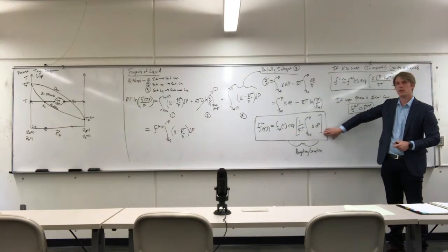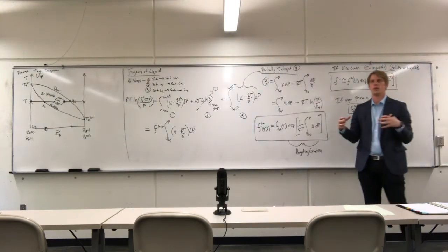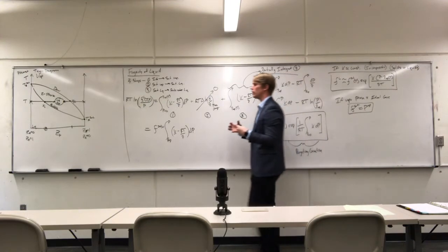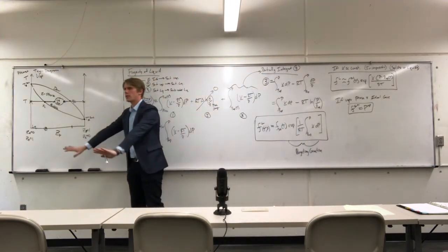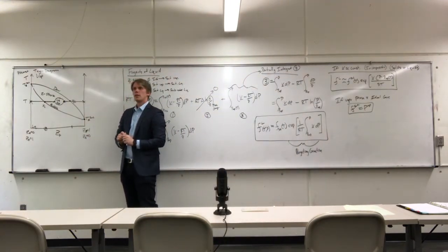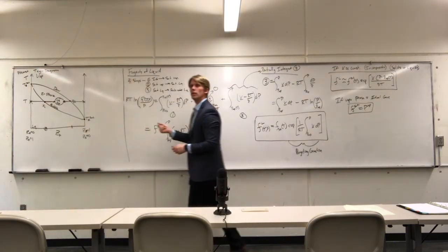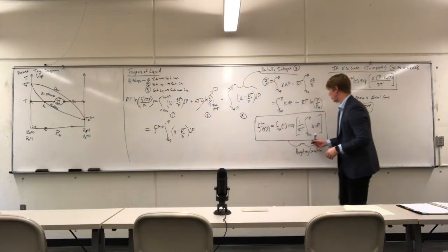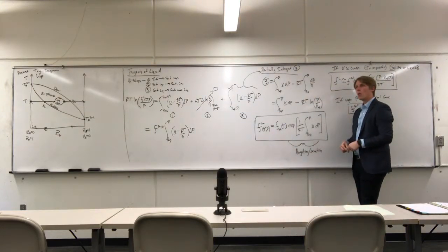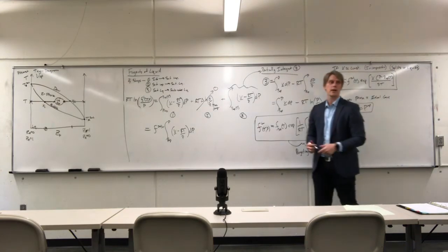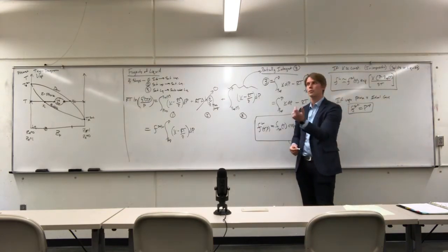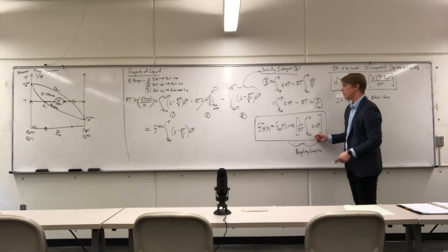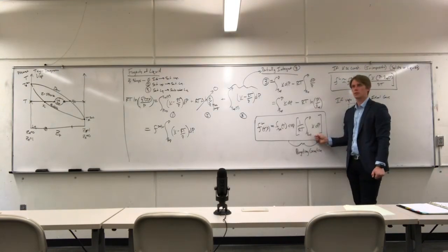So if we're doing this phase equilibria for a really, really high pressure fluid, a fluid that would naturally be very solidly in the liquid state, but then you introduce a new material, you can have interesting and complex phenomena that happen for multi-component systems. That's where the Poynting correction is going to be really important. Or if I'm looking at a crystallization process of a high pressure fluid, the phase transition from a liquid to a solid, I'm also going to need to know the fugacity at that arbitrarily high pressure as well. So that's the motivation for why we're going through all this tedium at the moment.